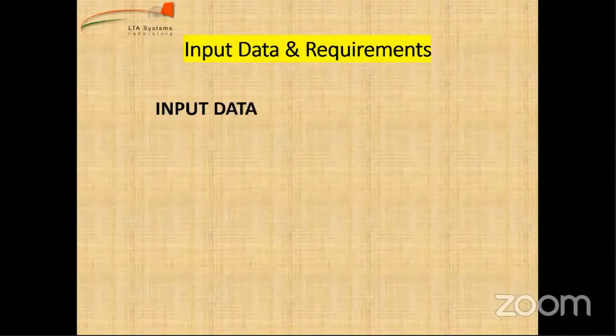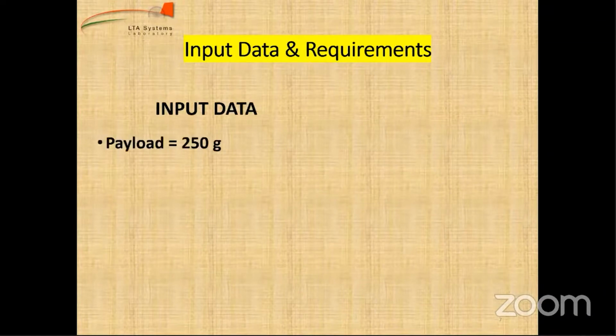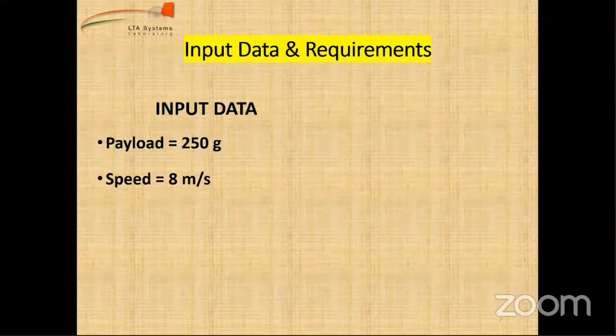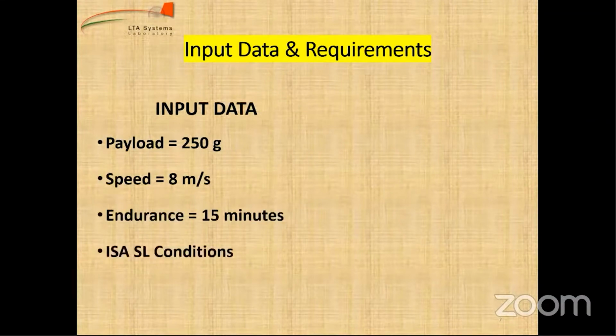So now, input data. This is extremely important as far as today's session is concerned. Like I mentioned previously, the payload will be 250 grams. The speed is something that we have set based on experience, that is 8 meters per second. The endurance is 15 minutes and ISA sea level conditions. Can any one of you tell me what the ISA sea level condition is?